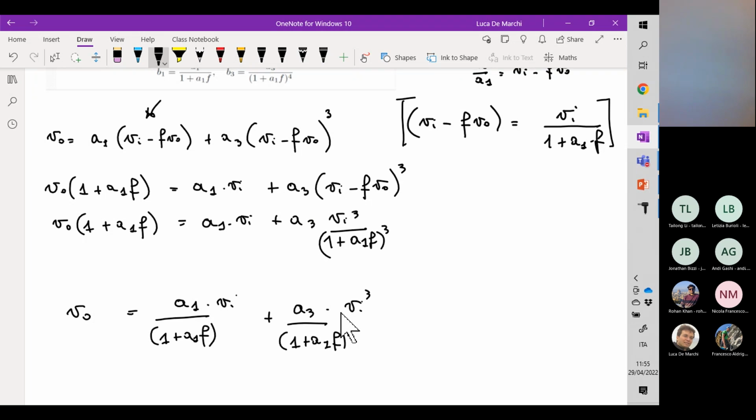The phase curve is here, and this is a very borderline situation, because the distance between this point and the minus 180-degree curve is relatively small. We can say that we meet the Nyquist criterion, but we are at the very limit of it.